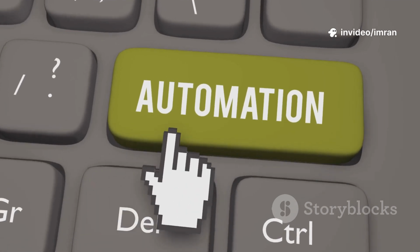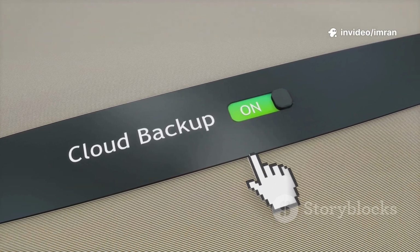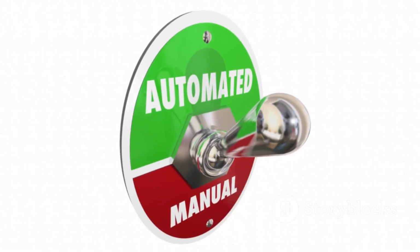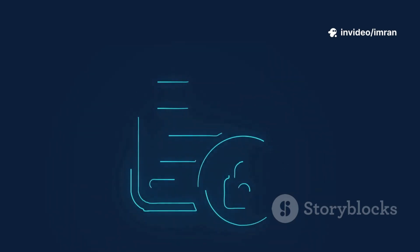AutoCAD also has a helpful autosave feature, which automatically creates a backup file at regular intervals, typically every 10 minutes by default. While this is a great fallback, you should not rely on it as your primary method of saving. Taking manual control by using Ctrl+S frequently is the most reliable way to protect your work.